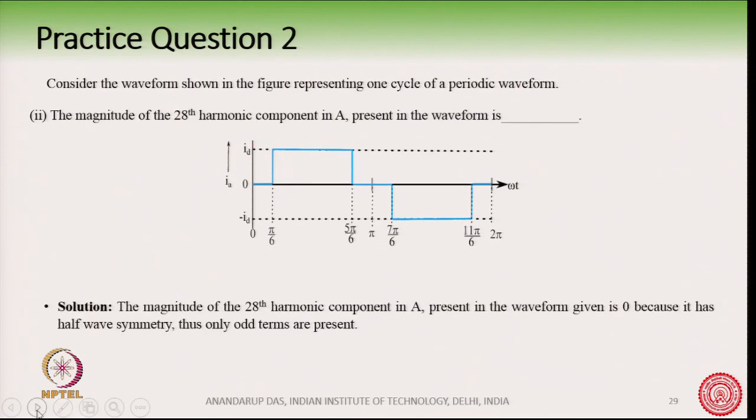Now, the second question is, what is the magnitude of the 28th harmonic component present in the waveform? When you calculate the 28th harmonic, you have to be careful, because this is an even harmonic. Does an even harmonic exist in the waveform?